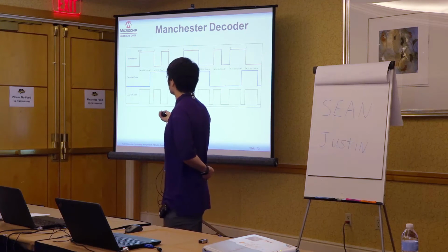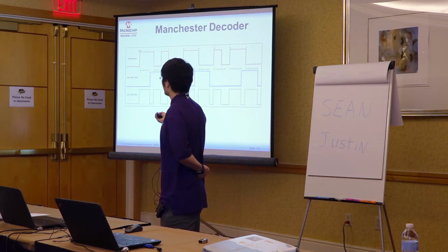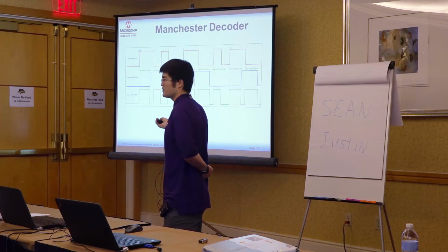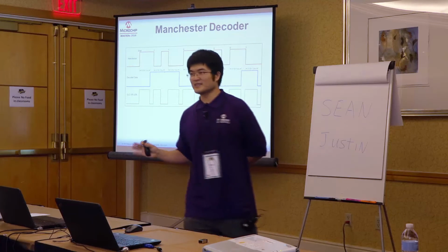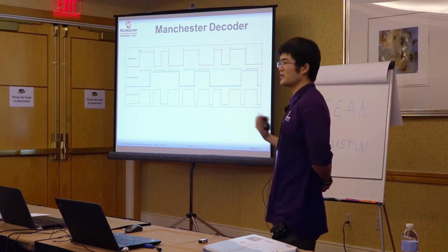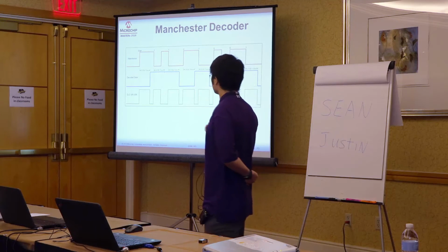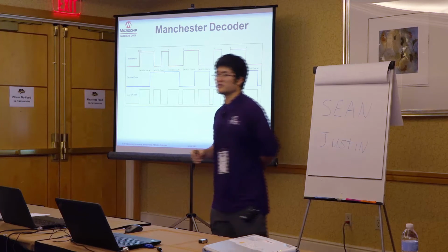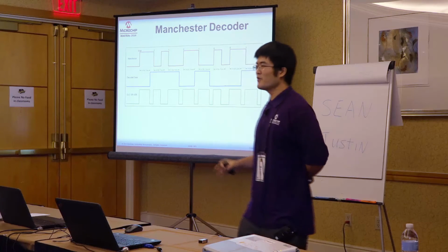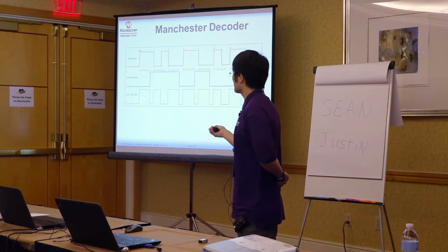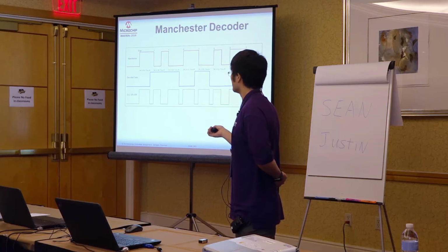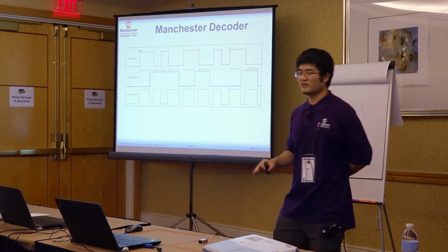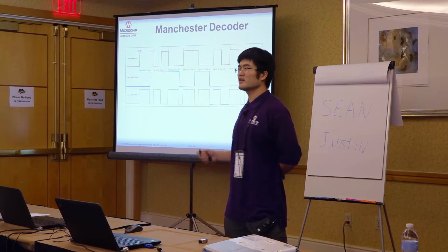So now we are pretty close to what we want, right? We want to synchronize with this clock, and we want to do our sampling at 3/4 of the time. Sometimes we get the right time, but sometimes we are 20%, 25% off because of the data pattern. So what we want to do is make this imperfect clock perfect. We want to extend those situations and make them a 75% clock source. That way, we have a perfect clock, we synchronize with our data rate, and we can do our sampling on the following edge of our recovered perfect 75% clock. So far, so good.